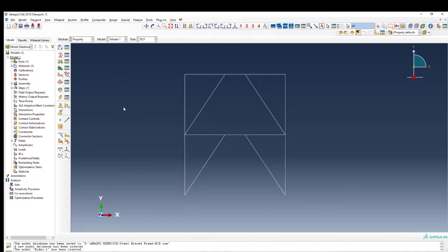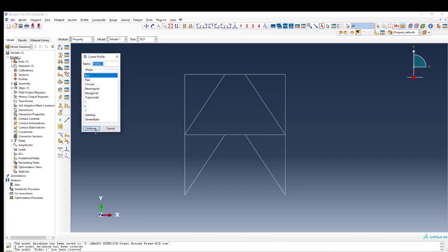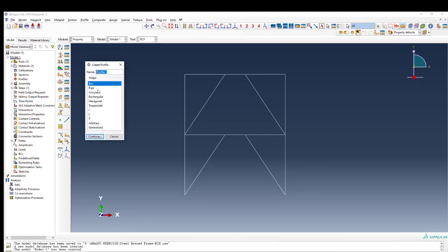The next is we have beams and columns. So we should define what we're using, beam elements. So we have to define some profile. We can call it column. That column is 400 by 400, and this is 20 by 20. So it's our H section.